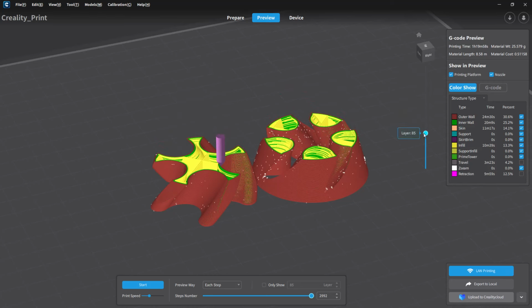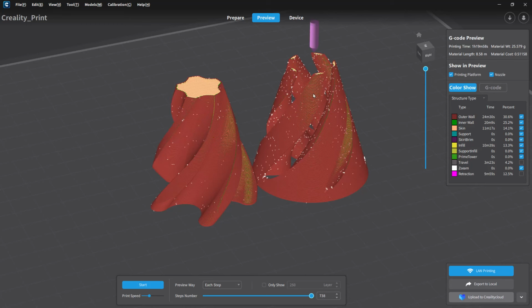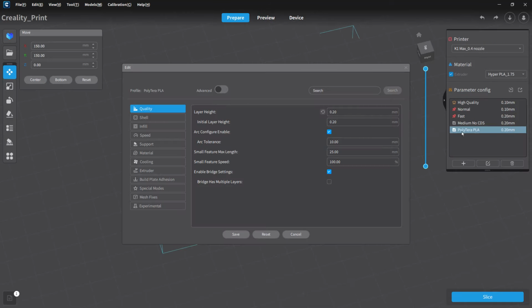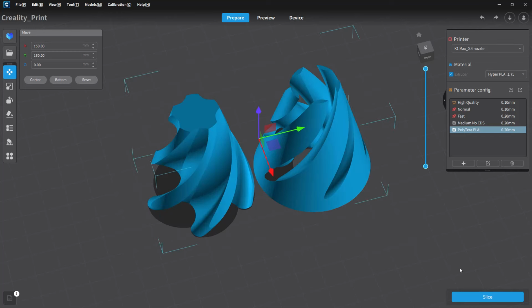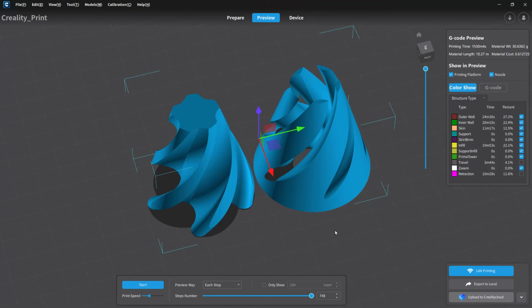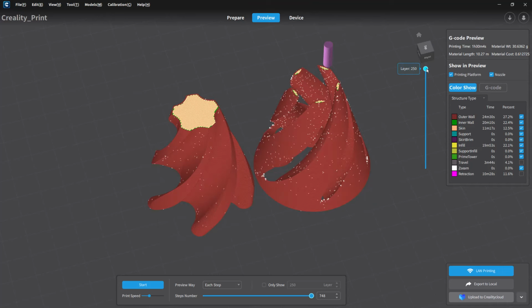These arms on the external piece, especially if you have a fairly low infill value, they're going to be pretty flimsy. So you do need to be careful, especially since we cut it out so low on the bottom. So you may find yourself going into your infill options and maybe increasing this to say 15 to 20% just to make it a bit stiffer. That would help those pieces out. It'll still work fine. I haven't actually broken one of these things yet, but they do tend to flex and move around quite a bit more on that 5% infill. So play around with your own printer, your own settings.